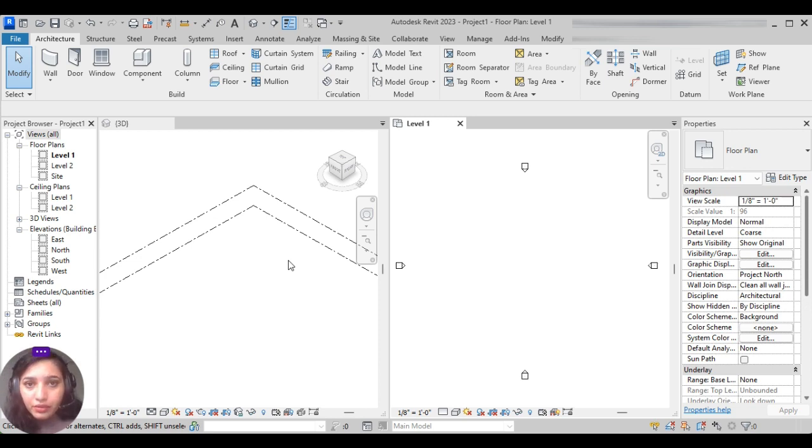As you know, Revit follows real-time modeling, which means whenever you draw a component in one view, you will see that component in all the other related views. So what if we want to draw something that we only want to see in one view? For example, we want to make some 2D details, and we want all of those details totally detached from all the other views, because that's just a part of detailing that we want to do. In that case, we use a detail line.